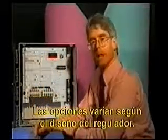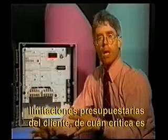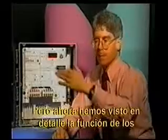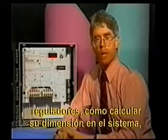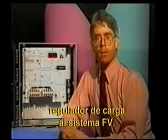Different types of regulator designs will involve different numbers of options. Whether you choose these options or not depends a lot on budget constraints, the particular client that you're trying to suit, the criticality of the load, other factors that you would weigh. But now we've taken a good look at the function of regulators, how they should be sized in your system, and some of the other functions that might make the complete aid that a charge regulator gives to a photovoltaic system.